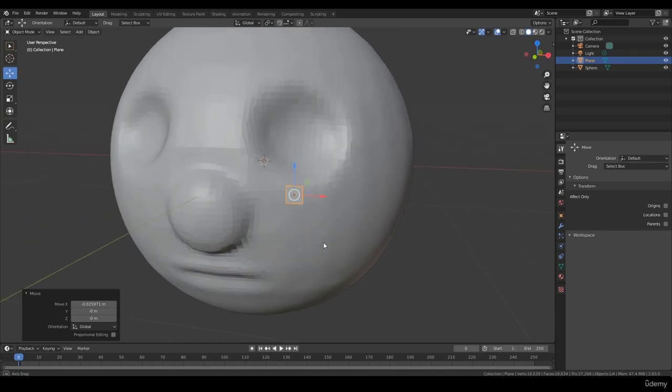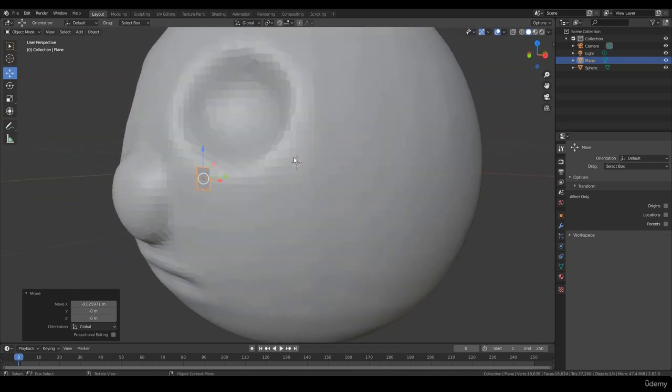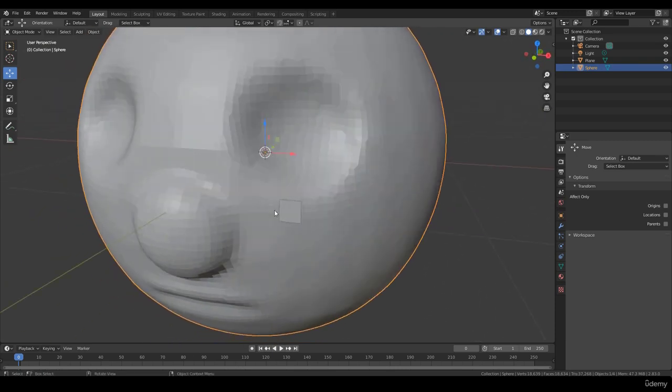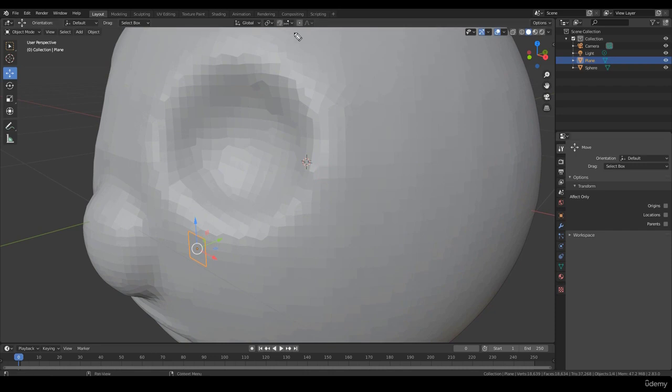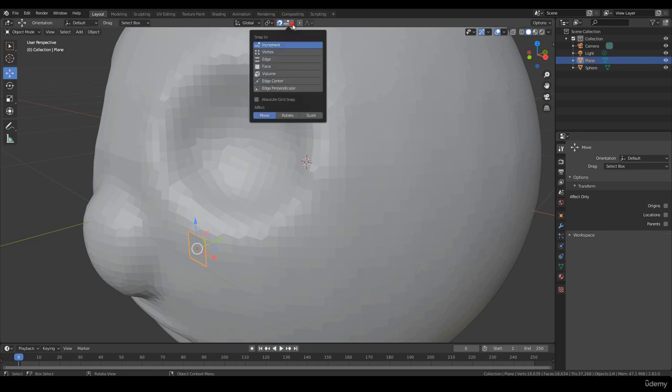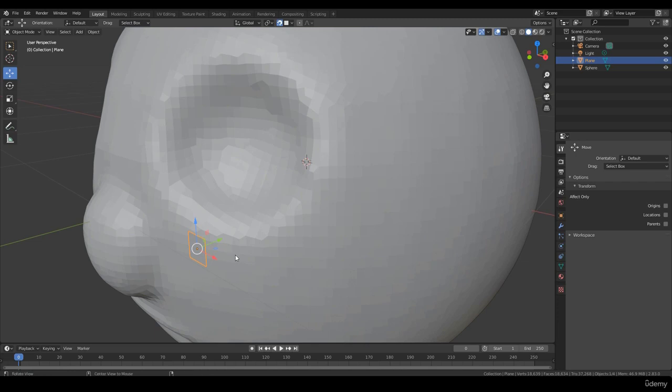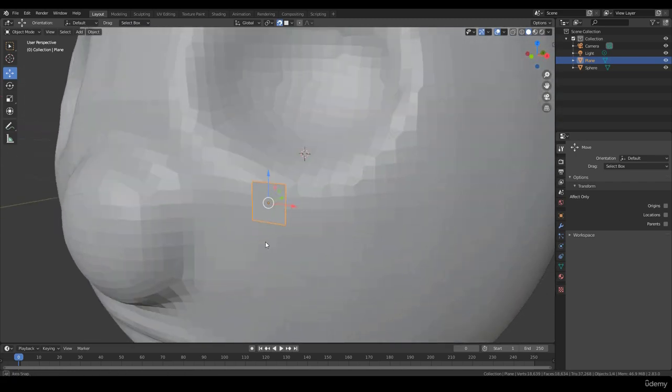After you create a new plane, we need to have that plane snap onto the surface of the character's face. In order to snap this, we need to turn on snap, and we're going to mess around with the properties there. Let's turn on snap, go to the drop-down and make sure you have turned on Face, and you're going to see some more properties here. Snap with Closest, so it will snap to the closest target next to the plane geometry. Let's turn on Project Individual Elements, so it will project the elements onto the surface of the other objects. Now that's on, let's test this out.